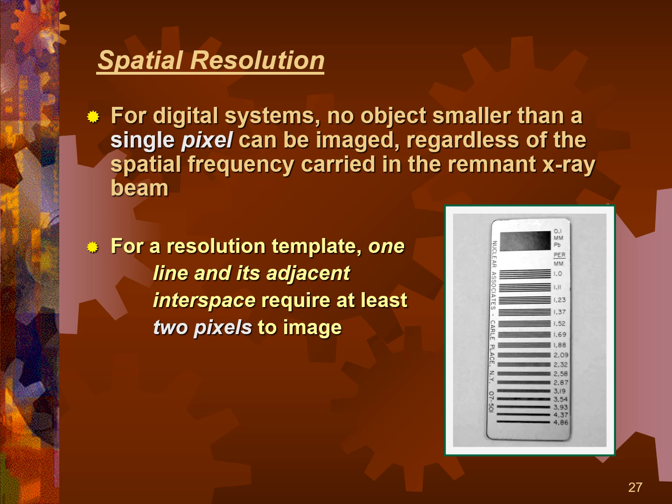Your pixel size, you need 2 pixels to create a line pair. If the object has a line pair that is smaller than 2 pixels across, then when you take an image of that object, you won't display that line pair. As long as the object is greater than the size of 2 pixels across, then you'll be able to display it adequately.